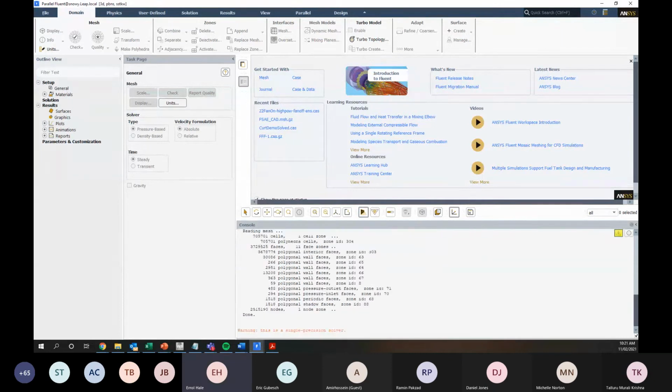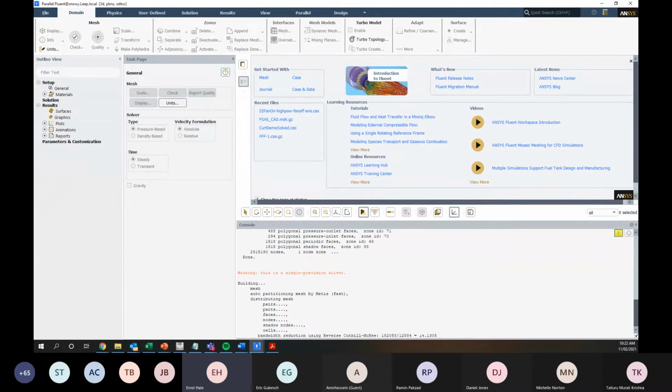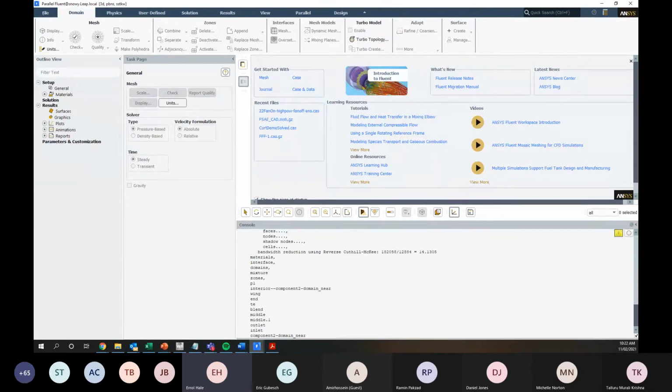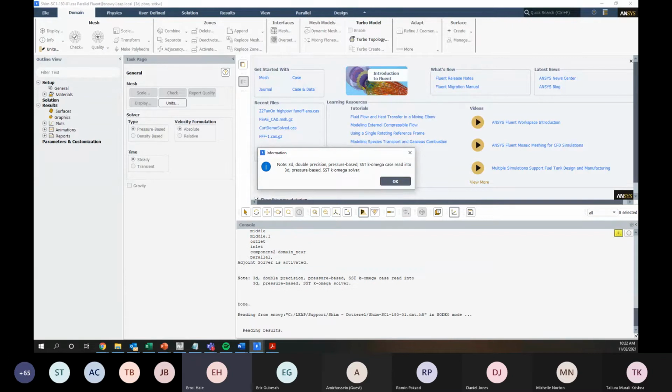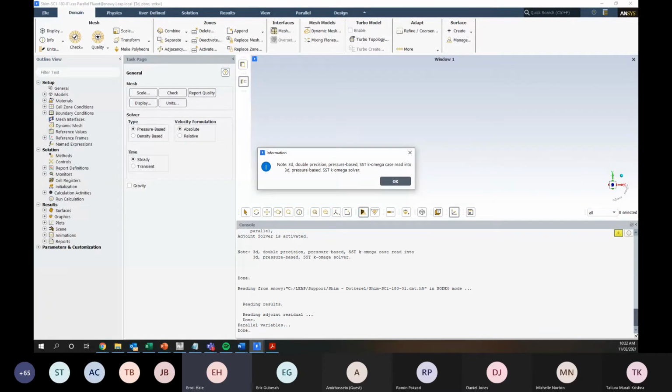Could you explain the difference between time step convergence criteria and solution convergence? And if I'm using the time step convergence, how could I make sure that the solution is converged? Well, they're both very similar, so there's not really any difference. They're both using residuals to assess convergence, but you're either solving steady state or you're solving transient. So in a transient case, you're converging every time step, and you should be converging within 20 iterations. In the steady state case, you can use as many iterations as necessary to get to a solution. There's plenty of solutions that can take upwards of 5,000 iterations to get to a fully converged solution.